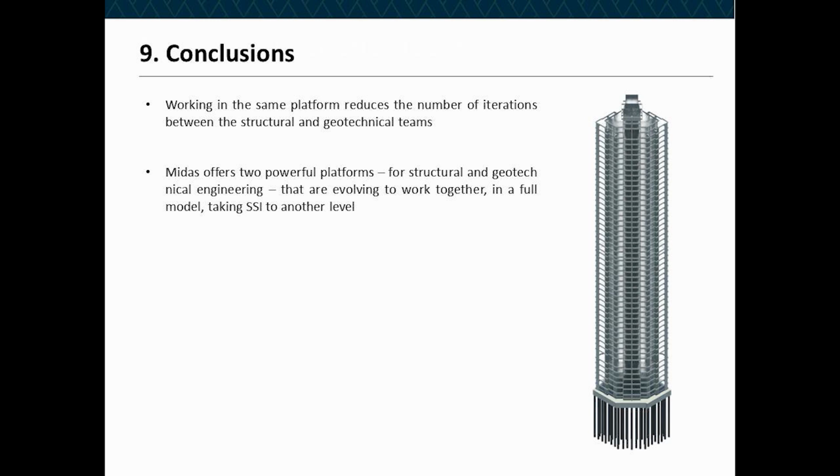So as a final thought, Professor Barata, who was an old foundation engineering expert in Brazil, would say simply: we need to measure. This means that for every effort that we make to evolve with complex models, we still need to measure the real behavior of the structure. In this particular case, every column of this building will be monitored for vertical displacement since the construction of the very first story. This is to make sure that we are heading in the right way.